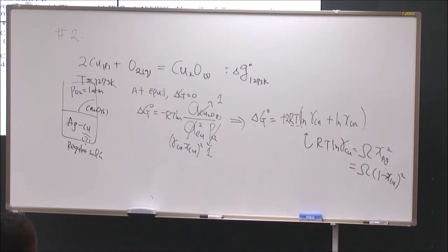So it's a similar question. Okay, now we have liquid lead, and then we have copper as impurity. And we are adding PbS into this solution. So the following chemical reaction happens to make a certain amount of Cu2S. So PbS reacts with the Cu and becomes Cu2S, and then PbS is reduced to Pb. And that's the chemical reaction. And this is 1823 Kelvin.